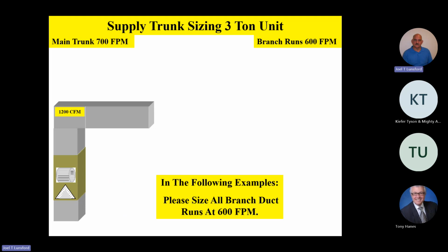And so this is a real easy way to design a duct system. I've done this for over 20 years, probably 25 years, and it works very, very well, gives you a nice quiet system and so on. The only downside, if you will, of this method is that your ductwork is going to be a little larger, so there may be a little cost difference between what you may normally have been doing and a little larger duct system. But it's well worth the money. It's well worth the installation difference because, frankly, it'll give you a really good duct system. It's going to be quiet and efficient, and that's the main thing.